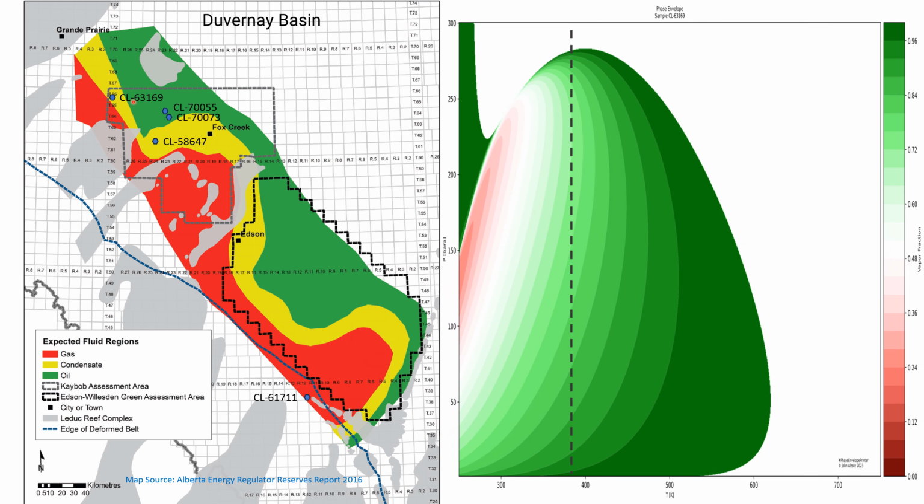My next fluid, 63169, is a richer gas condensate again, with higher C7+ content, as we can see, as compared with the previous fluid. And in this one, we can condense more, like 60 to 70% of liquids we get at this condition, right? Around 150 bar. And interestingly, dew point, no critical point, right? And then again, this one has an unstable region here. Basically, the dew points shoot upwards, right? Asymptotically.